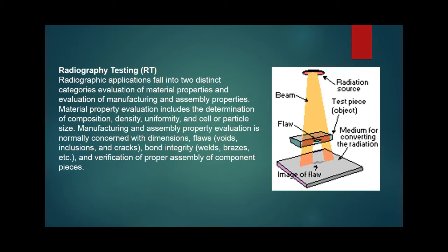Radiography, RT, is also known as XT, X-ray testing, SRT, source radiography, radiologic testing, gamma radiography, and neutron radiography testing. All these are part of the radiographic family and are dangerous, expensive, and popular. The ability to see inside things and provide a permanent historical image makes it one of the most popular NDT inspection methods. Radiography testing is the use of X-rays or nuclear radiation or both to detect defects in materials and to present the images in recorded media.